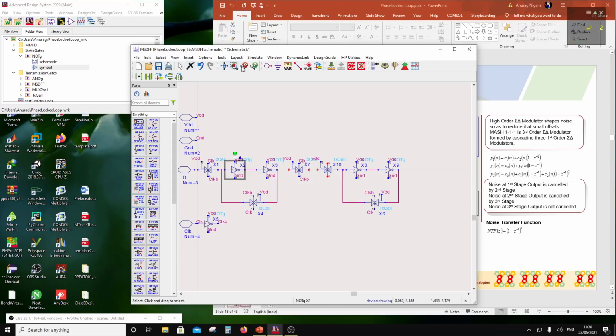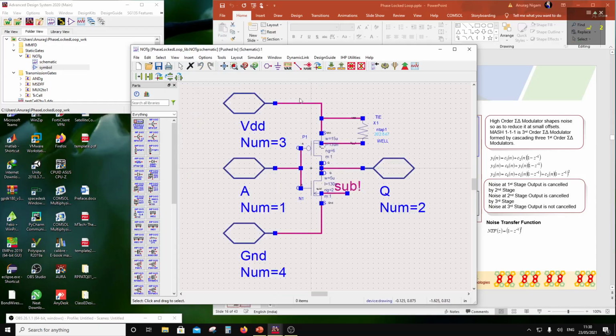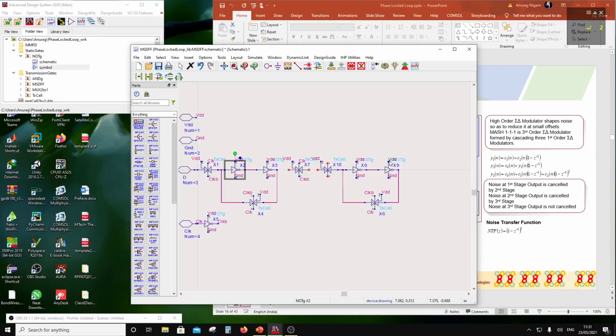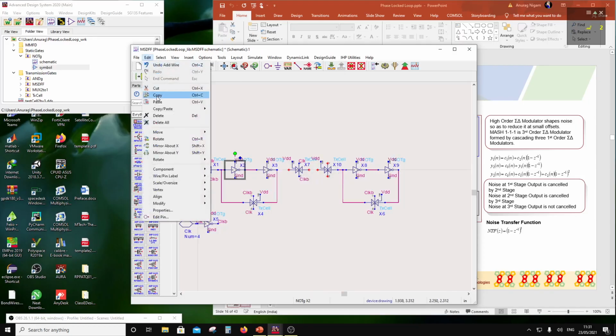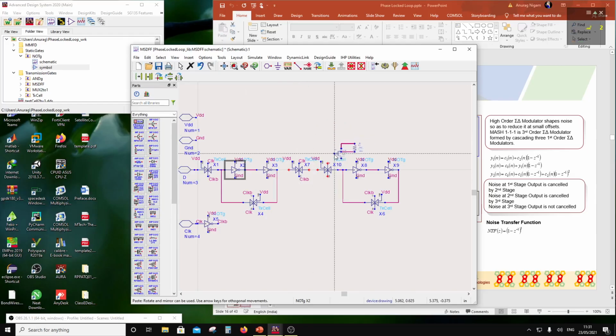So I can go inside and just copy that PMOS device. So I need this PMOS device to pull that node up. So I'm going to say edit copy, and then I'm going to say edit paste over here, and I want to pull up this node with the reset, right? So when this goes low, right, when this goes low, then this path is disrupted,